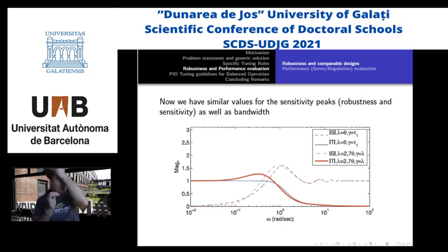But now we start modifying the design of the regulation. Is regulation because at the end, gamma is equal to lambda, okay? So it's a regulation design, but the initial value of lambda is increased a little bit till we reach the value of 2.7 theta, and then this makes the maximum sensitivity peak of both designs at the same value. But they take the maximum at different frequencies, so both designs will not be, of course, exactly the same.